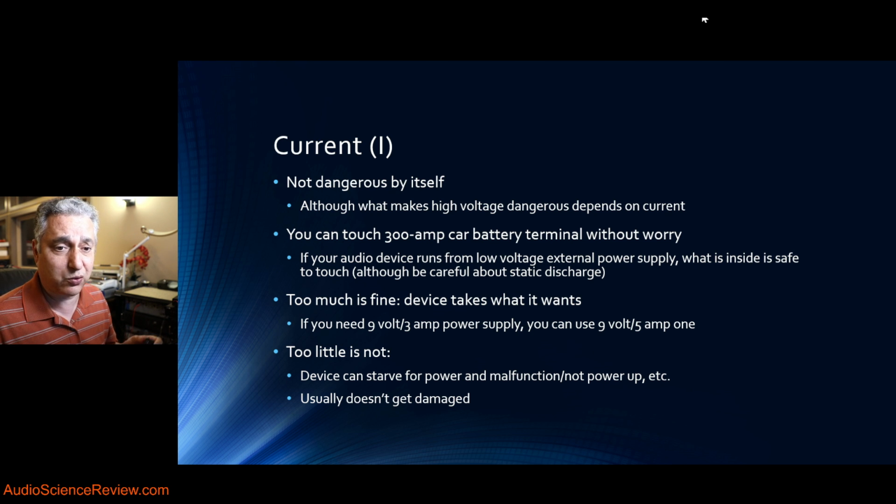Just do not sweat the details of that. A lot of times I get questions on a forum. People send me messages: I found a 24-volt power supply, and instead of 5 amps, it's 7 amps. Is it safe to use? It is absolutely safe to use. If it's compatible, if the voltage is the same and the connector is the same, do not worry about it. Basically it costs you more money for more current and more size and potentially less efficiency, but otherwise it's fine. So know that current is drawn as needed. Voltage is always used all the time at full amplitude. Okay.